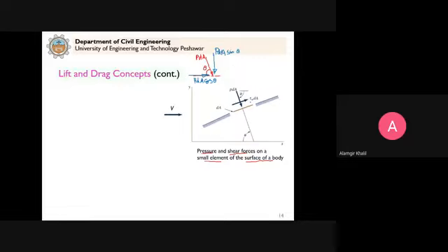And then next I have to resolve this force here, tau W. Tau W is what? This is the wall shear stress. Whenever a subscript W appears, it means that it is the wall shear stress. So times dA, this is the shear force. Clear? So now how to resolve this into components? Again you can consider the trigonometry here.